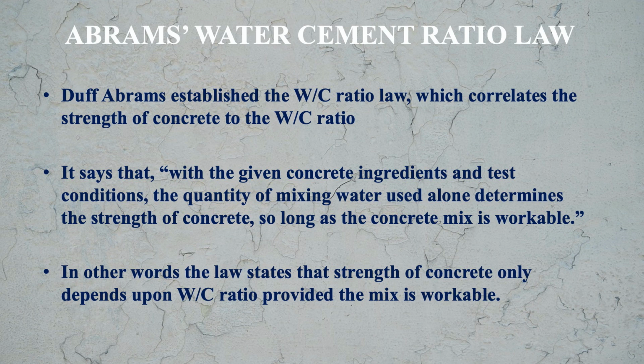So this is the statement that there are two parameters which are fixed. These parameters are concrete ingredients and the test conditions. These are fixed, and with these fixed conditions, quantity of mixing water will determine the strength of concrete. This is the law. In other words, it says that the strength of concrete only depends upon water cement ratio provided the mix is workable.